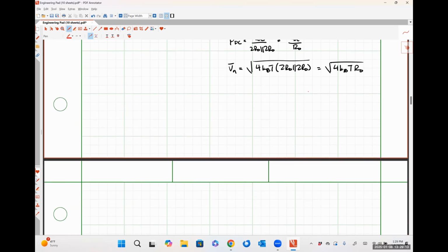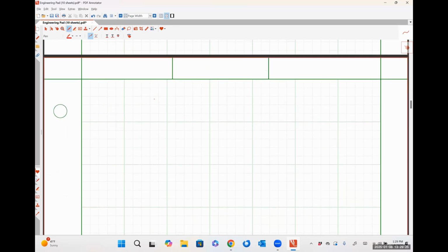So the second version of the differential sensing, or double-ended ratiometric sensing, is effectively using two piezoresistive sensors, okay? It's going to look almost exactly the same circuit, but we are going to have a VDC here. So we're going to put a piezoresistive sensor here.